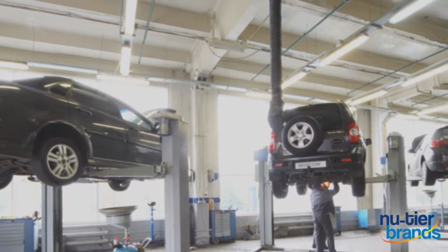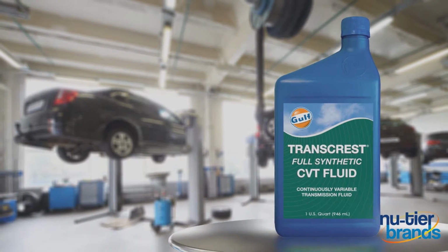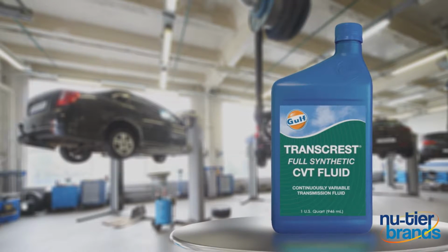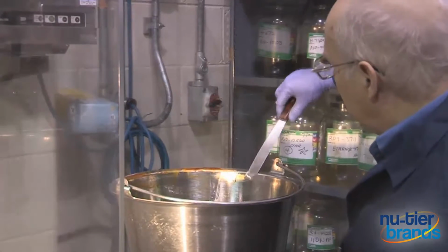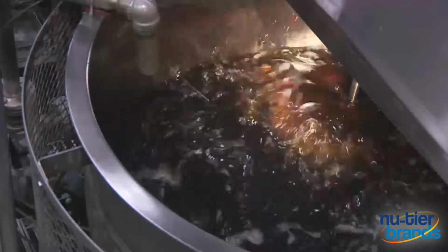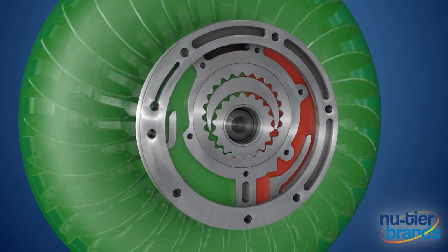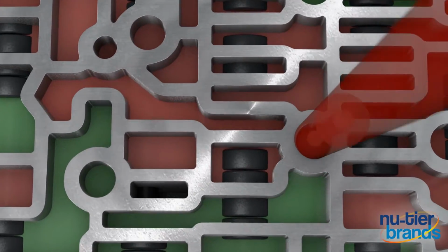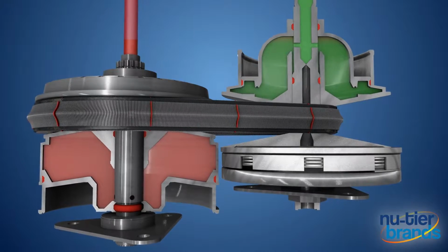There's one component of the entire CVT system that's critical to all the parts working together properly. It's the Continuously Variable Transmission Fluid, or CVTF. The CVTF is a precise blend of different chemicals because it does a lot of different jobs. It works as a hydraulic fluid in the torque converter and oil pump, and also in the valve body, which actuates the changes in pulley position to change gears.